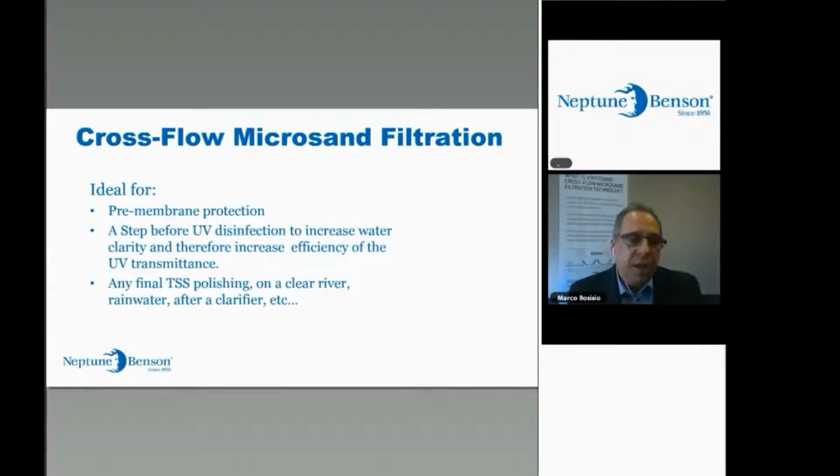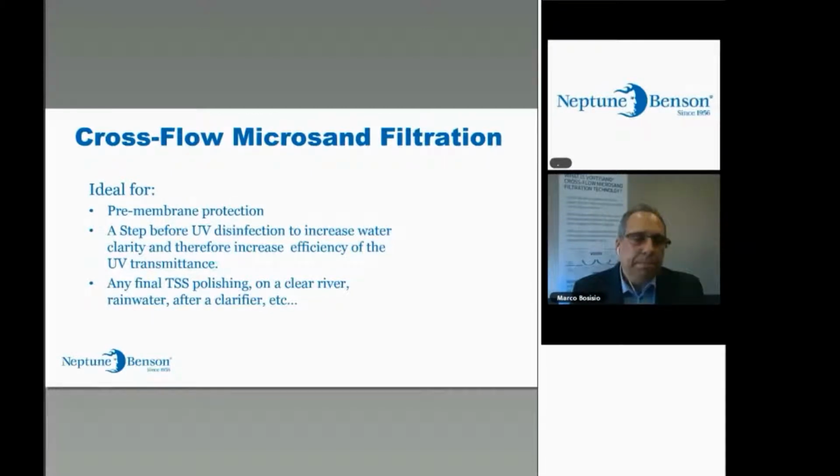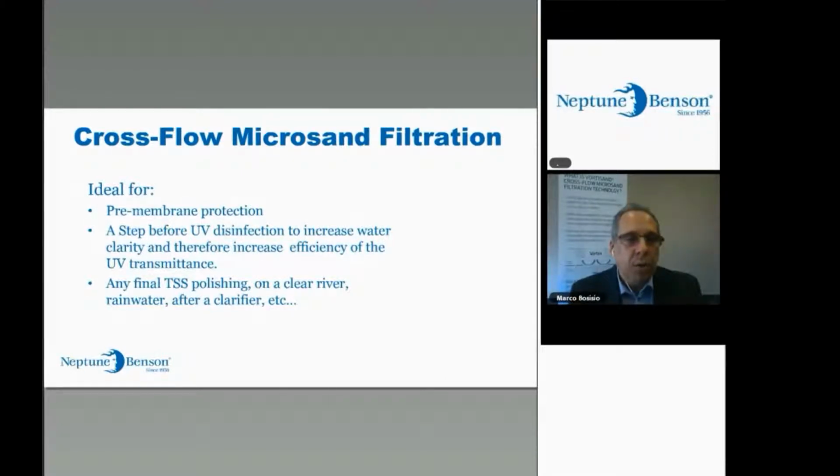It is obviously a very good system for UV disinfection, as it increases the water clarity and therefore the UV transmittance, and increases the UV efficiency. Of course, it can also be used as a final TSS polishing. We've seen different treatment chains in Abby's presentation. So it can be used in different places where multimedia or just filters are used.